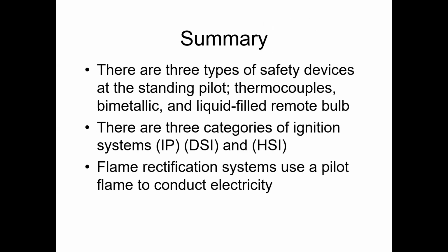All right, so in summary, there are 3 types of safety devices for your standing pilot: your thermocouples, your bimetallic devices, and your liquid-filled remote bulbs. You've got 3 different types of ignition systems: your intermittent pilot, IP, your DSI, direct spark ignition, or your HSI, hot surface ignition.